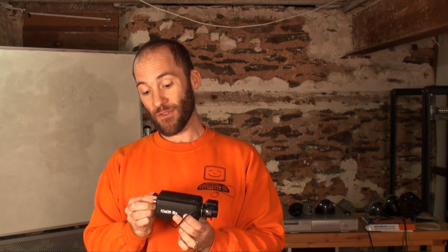What you're going to have to remember though, and this is where it can bite you in the butt if you're buying these for clients, is if you're buying box cameras for clients, remember it's generally not going to come with the lens, and it's not going to come with the mount. This lens can cost an additional $100 very easily, and the mount generally costs an additional $5 to $10. So if you're doing a 16 camera system, that means you just lost $1,800 on the project if you screwed it up.